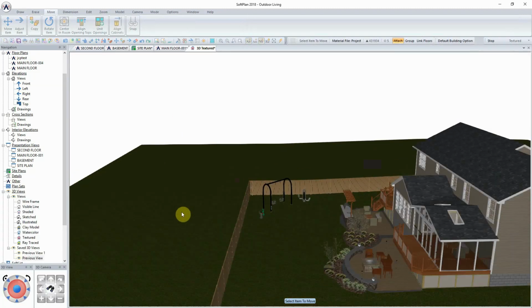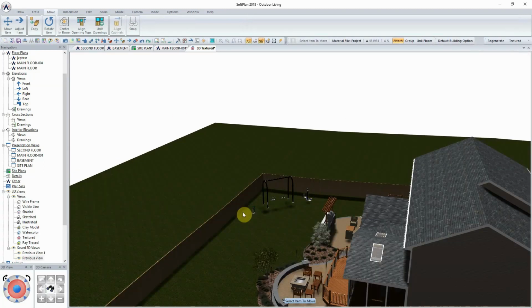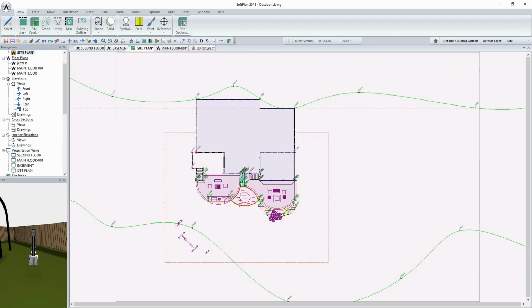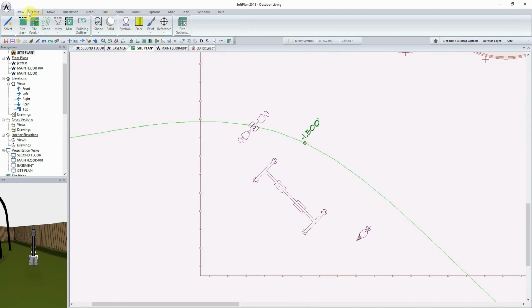We see the symbols being placed, and then we may want to mulch around this area here. And so changing into site mode and zooming this area up, I'm going to select the draw, site work, planting bed, something we've already done. Now there's two different ways this could be done. Obviously we could come in and place some railroad ties or a stone wall. Or in this case, I'm just going to select the spline option and sketch more of an organic type feel for our